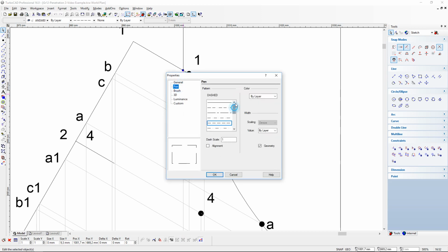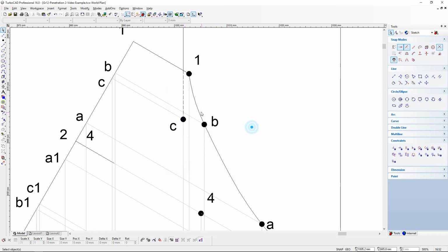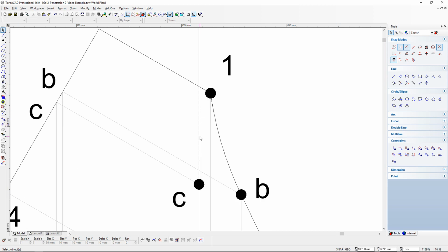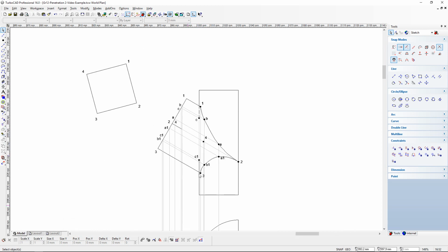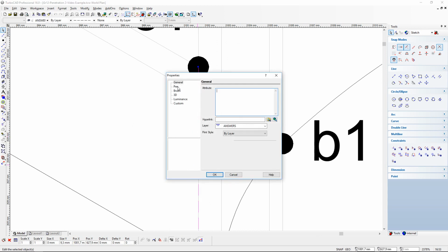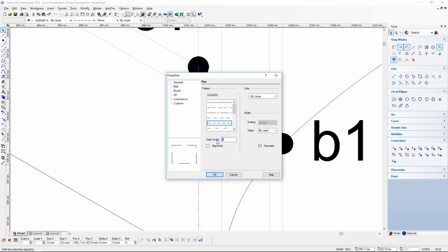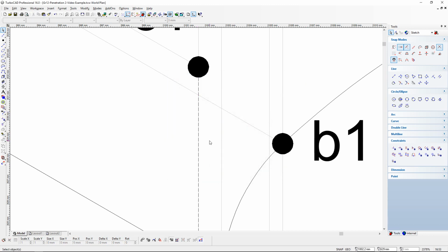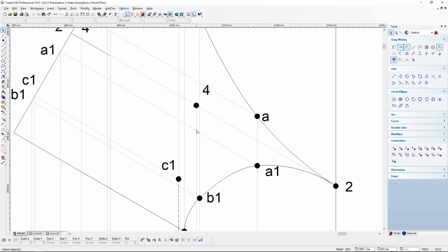Go and place it as 0.3 millimeters. Now the intervals are more clear, and I will do the same here with the hidden detail. On a printout, this will just look better if I use this at the scale of 0.3. There we go. Now that looks better when it's on a printout.